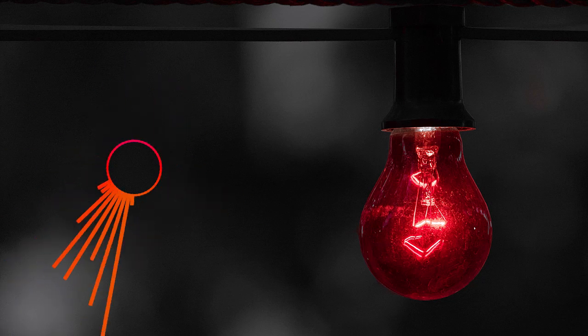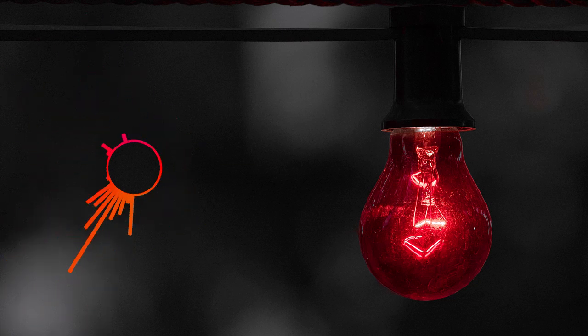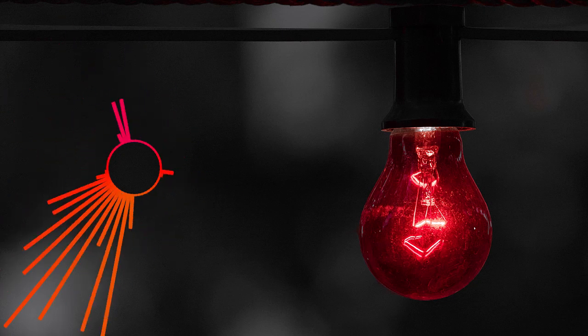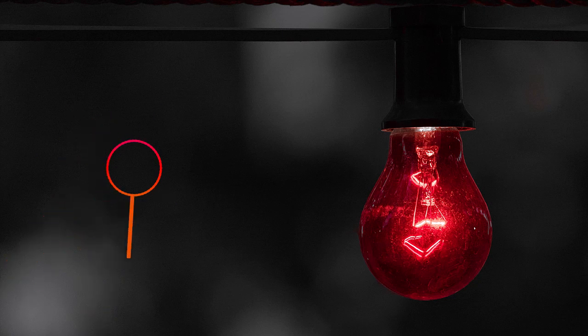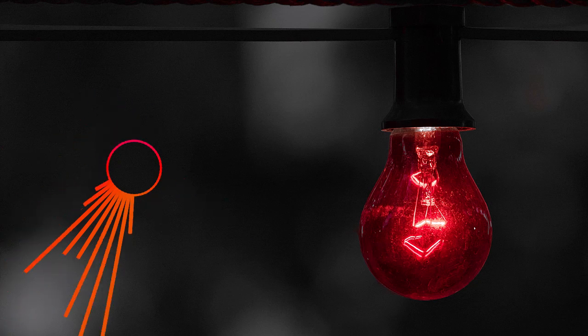Lumen depreciation compensation is a control function that automatically reduces brightness at first when the bulbs are new and slowly increases it as the bulbs get older. That way, the light level stays consistent over time, and energy isn't wasted when the bulbs are at their brightest.